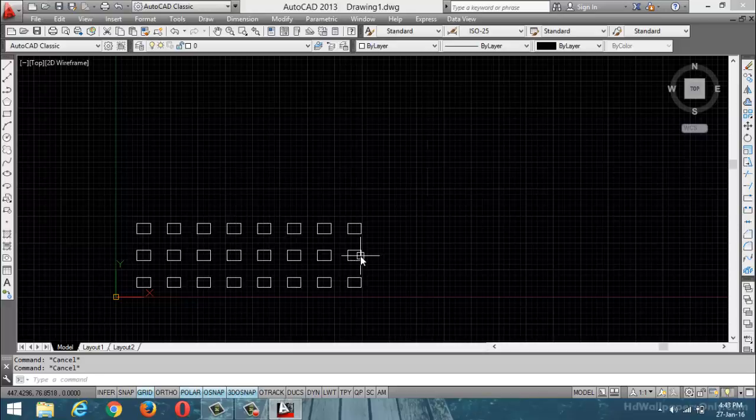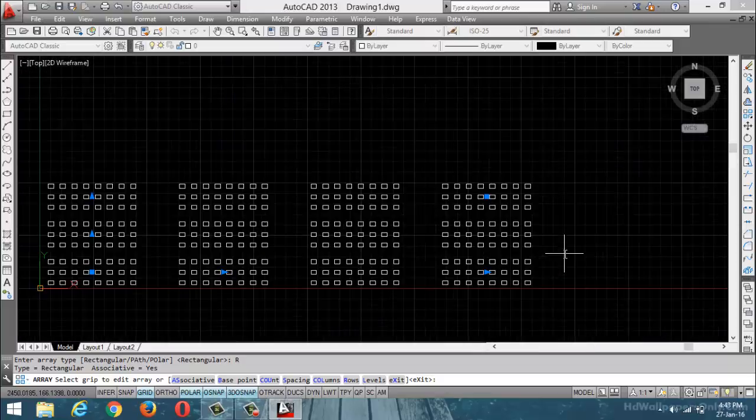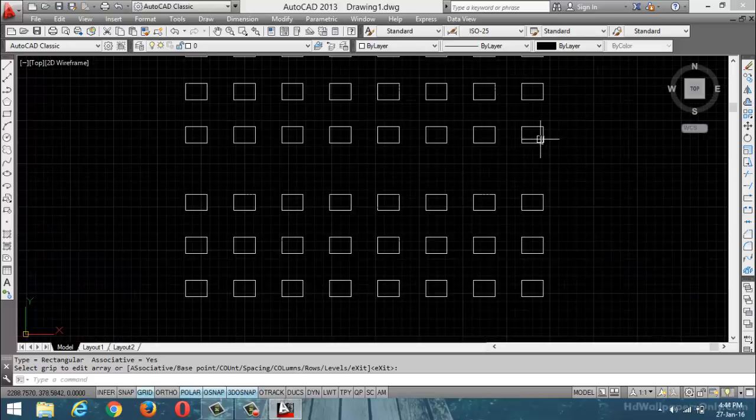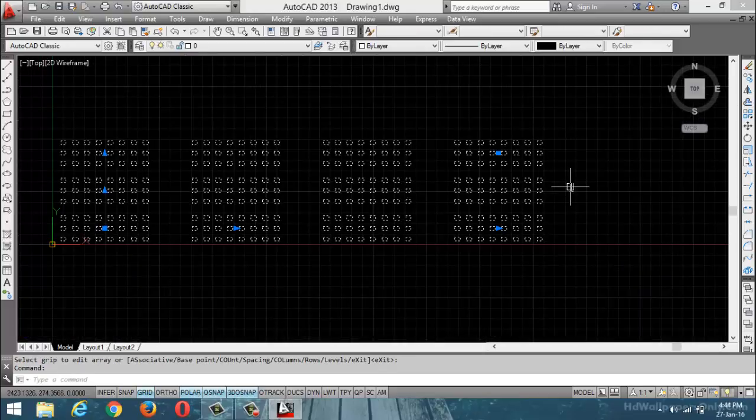Okay. Now see here, my next design requirement is that I am going to prepare an array of array. Again AR, select this one, enter. Select the rectangle. What is the design? First we design one rectangle, we apply the array, then again we can create an array of array. Then again I select a single element in the array. What happened? The total elements will be selected.